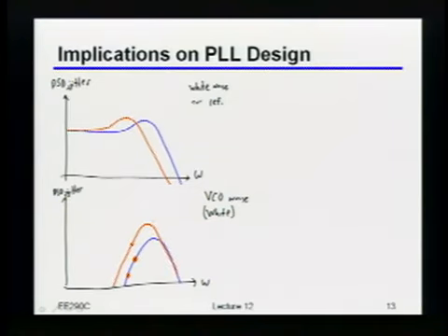So it does indeed shift to the left because I did move the loop bandwidth down. So the point at which you start rolling back down does move to the left, but the whole amplitude moves up, okay? Because really all I did by reducing the loop bandwidth is reduce the open loop gain. If I reduce the open loop gain, then whatever was showing up after that gain, I'm now twice as sensitive to, okay? Does this make sense to people?